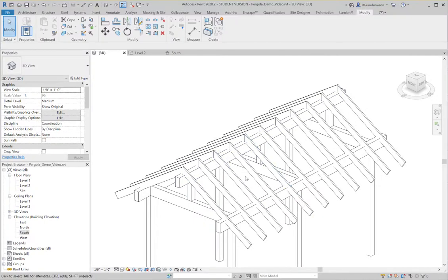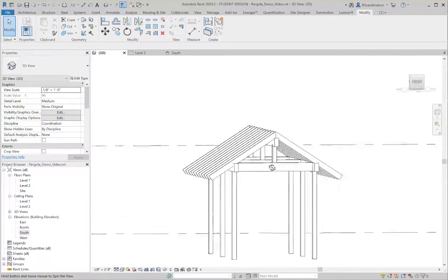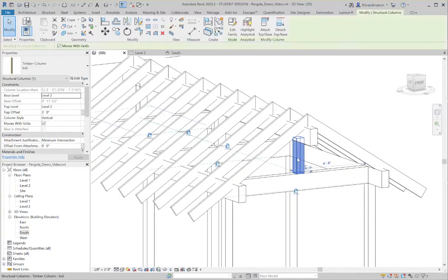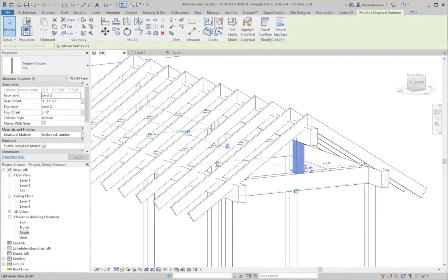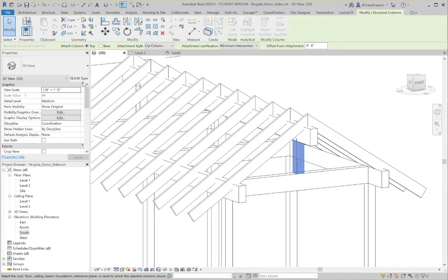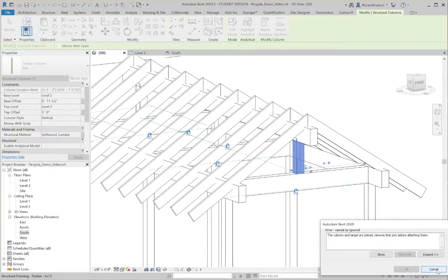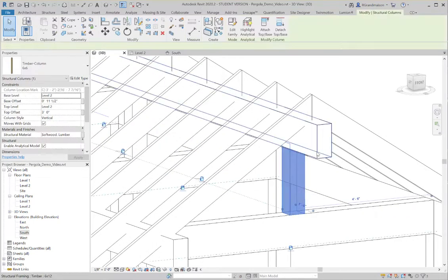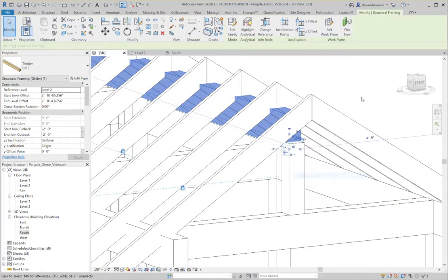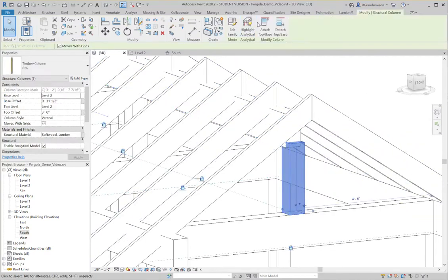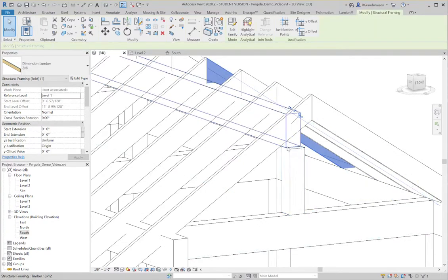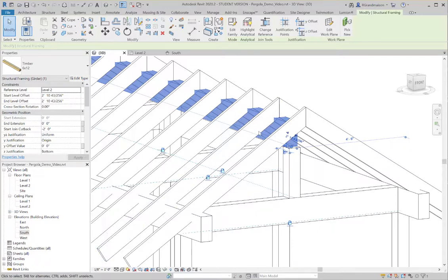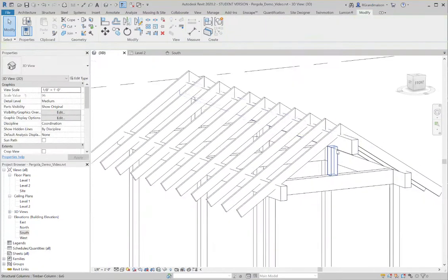All right, so let's talk about finishing up on these. Let me see, I want to detach this one. Let's detach top base. I'm going to say detach all, and then I'm going to select this one and say attach top base again, and click on this one for the top. Cancel. I'm going to disallow join on this. So I'm going to right click here and say disallow join. I'm going to take this one now and say attach top base, top here, and that's fixed now. And now I'm going to select this one and drag this out some like that. Okay, so that's fixed.